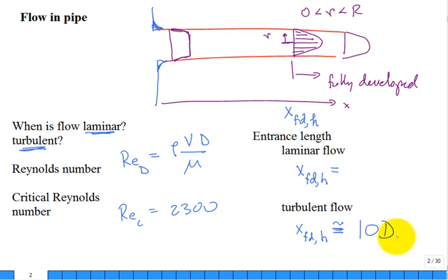And if you work in fluid flow and pipe systems, you'll just see 10 diameters, 10 diameters, 10 diameters. It continues to come up. Often after a bend or a turn, you want to reestablish the flow to be fully developed, where the velocity profile is not changing as you're going down the pipe anymore. And so they'll say, okay, if you want to put a flow meter into the system, that flow meter anticipates a certain velocity profile, hence it needs to be located 10 diameters down from the last disturbance, like a bend or an elbow. You'll see that a lot.